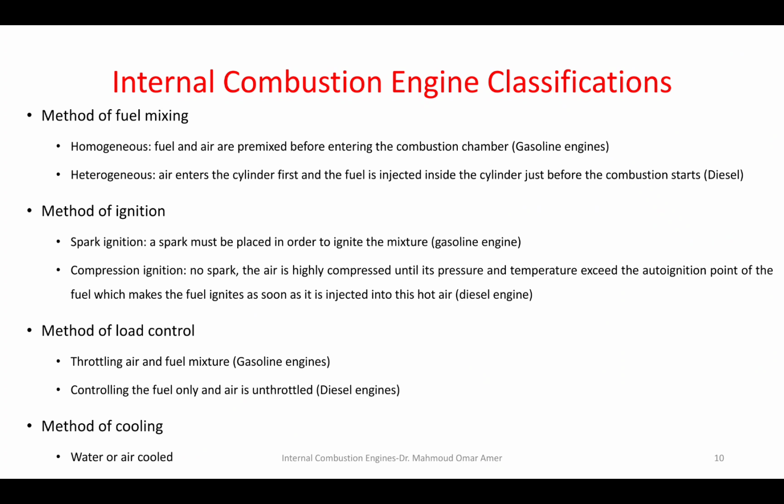What? Inside here. Exactly. When you open the throttle valve, the amount of air increases. As the amount of air increases, the airflow sensor senses this increase and accordingly increases the fuel injected at the intake valve. So you increase the air, and as the air increases, the fuel is increased accordingly.